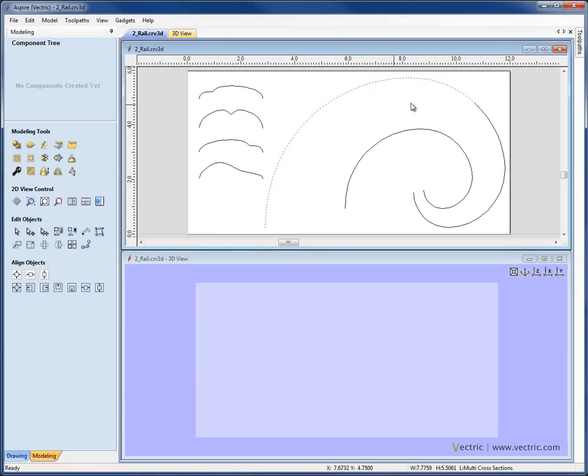So as we create shapes with the two-rail sweep and they twist around, you saw earlier how if you have a discrepancy between the lengths of your rails, it's possible for the shape to get twisted. The best way to deal with that is to break the rails up into smaller pieces and make multiple sweeps in order to create your finished shape. This is also necessary if you wanted to create a shape that has more than 3 cross sections in it.